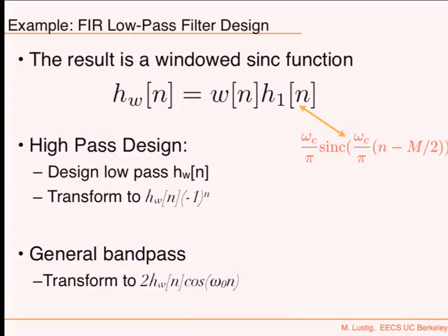Okay. So this is a low-pass filter design. Basically, you take this discrete sinc and then you window it. That's it. Window with a Hamming window. Basically, that's all you need. And you need to know, based on omega C and M, that basically squeezes the sinc or shifts it around. That's pretty much what it is. Okay? So it's very easy to design.